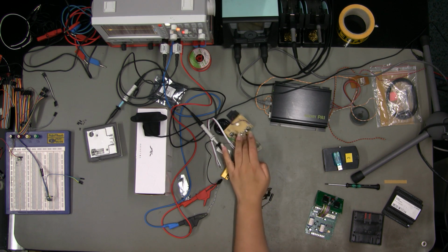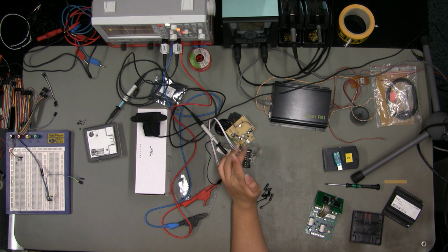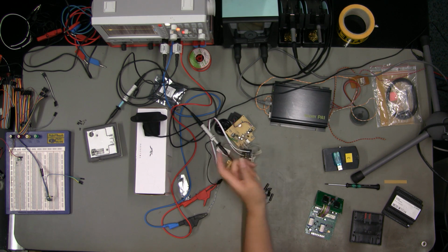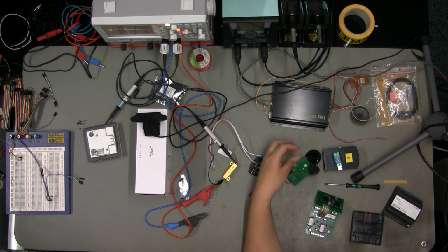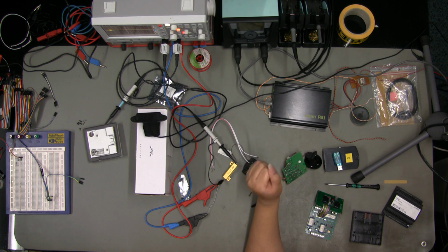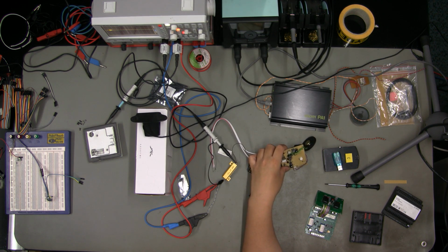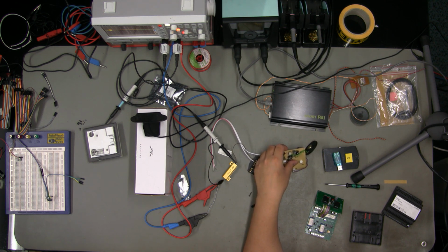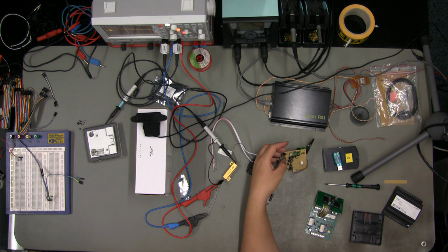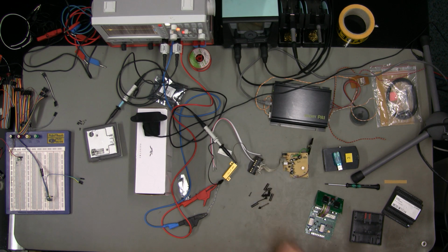So we have to take a closer look at this PCB, and maybe I'm going to have to even reverse engineer it completely, like the whole circuits, but that's fairly easily done, as it's just a single layer PCB. Before we're going to do that, we just look into it. But it really looks like this actually has a built-in amplifier for the loudspeaker here, because we have the second potentiometer and the 2 additional transistors, so that could easily be the case here.